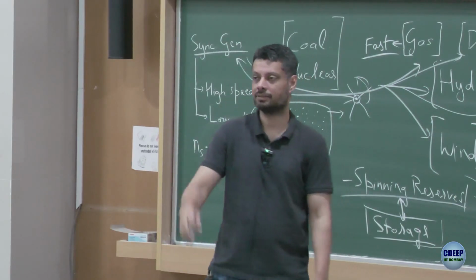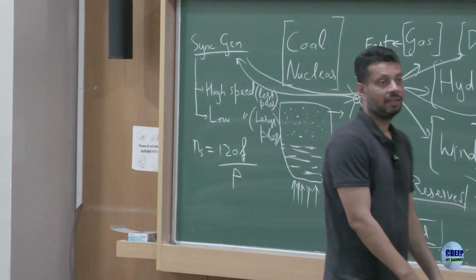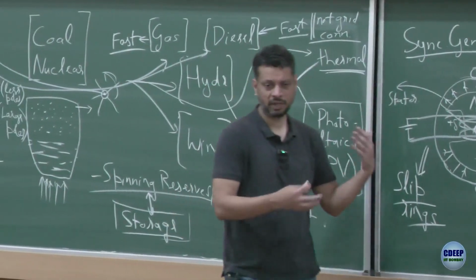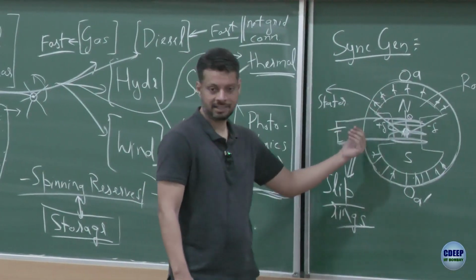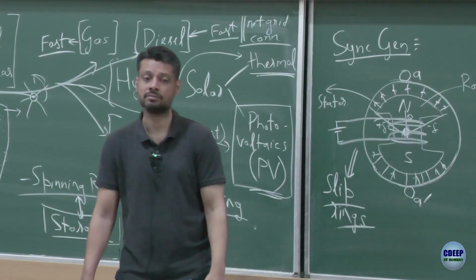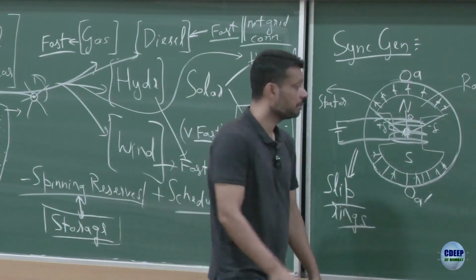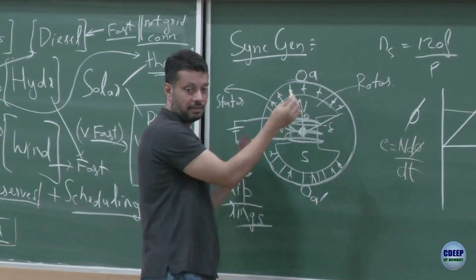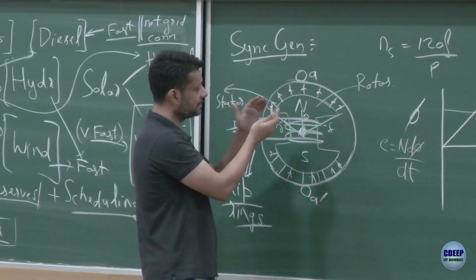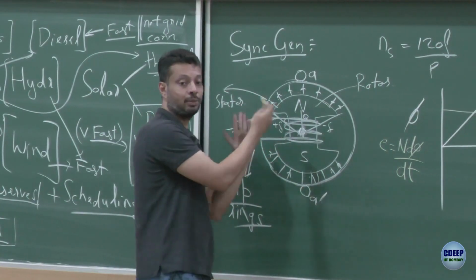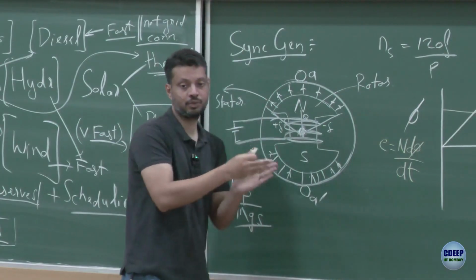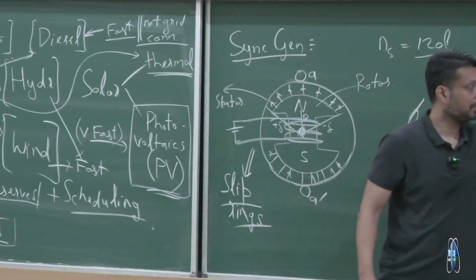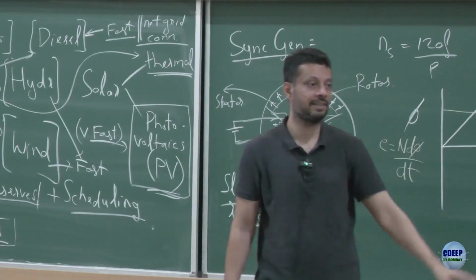We'll come to that, wait. So far is it okay? This is not based on any previous understanding, they are just seeing if it rotates. Because flux density is uniform, these lines are placed at equal spacing. So if you rotate by theta degrees, n lines come in; if you rotate 2 theta, 2n lines come in. Each line corresponds to the same value of flux density, because it is a uniform air gap flux density. That is the main part.